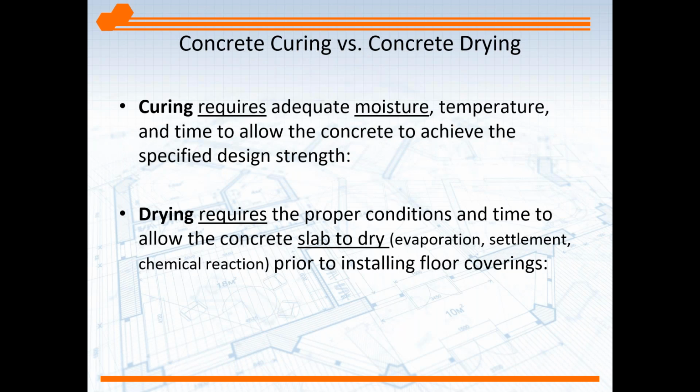Now, I think it's important to establish the difference between curing and drying. Curing requires moisture. Curing is really, in a sense, a chemical reaction. When you add water to cement, there's a bunch of chemical reactions that happen. Again, it's catalyzed or starts with moisture. You need an ideal temperature for that chemistry to happen, and it has to be over a period of time. But generally speaking, concrete is considered fully cured at about 28 days.